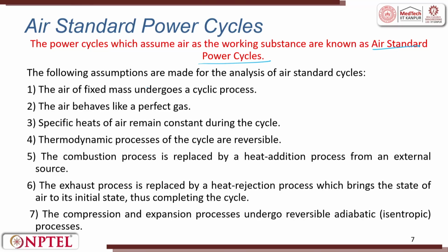The following assumptions are made for the analysis of air standard cycles. The air of fixed mass undergoes a cyclic process. Air of a fixed mass. The air behaves like a perfect gas. It does not have any friction, there should not be water, all those things. The specific heat of air remains constant all through the cycle. It is an assumption. The thermodynamic processes of the cycle are reversible.